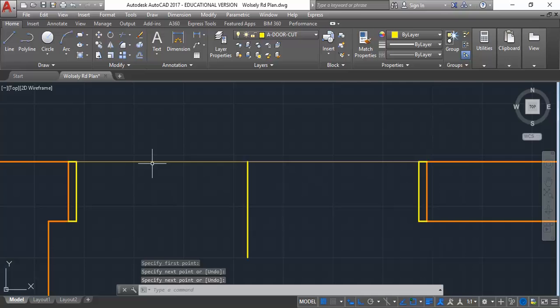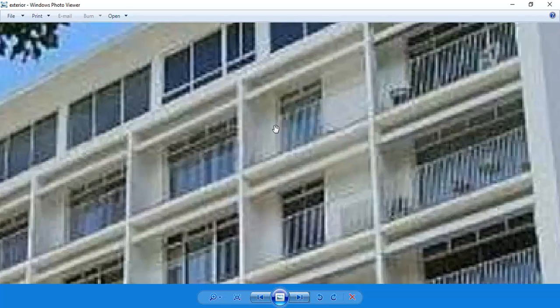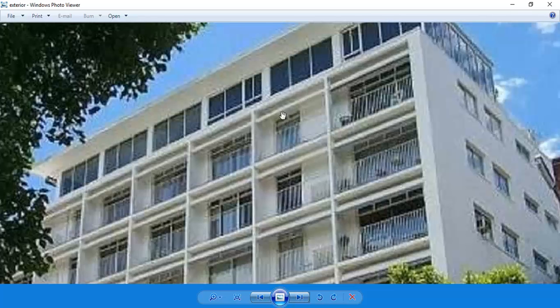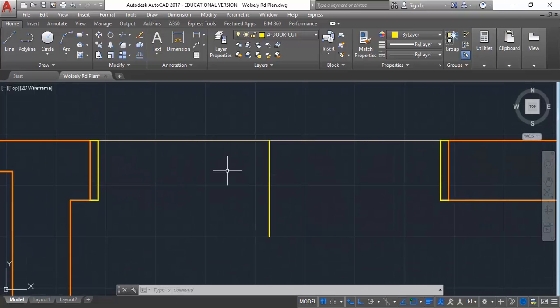And then if this is an aluminium door, which I think it would be, aluminium or maybe steel, but they look like aluminium to me. So it's going to be a probably a 50mm frame, and so I want them to overlap that amount.